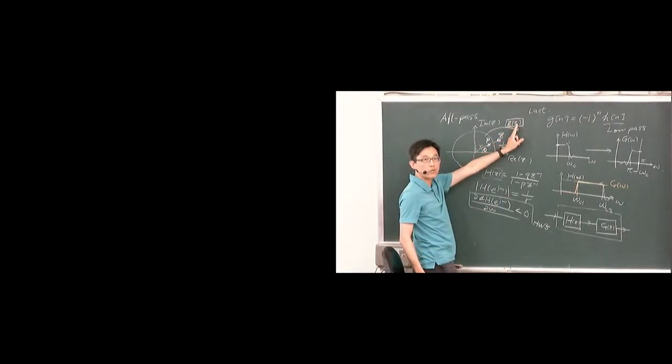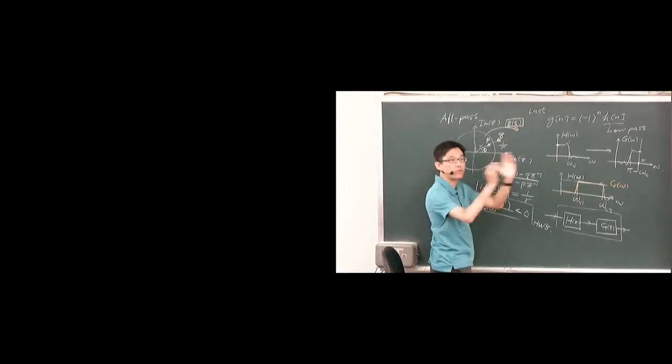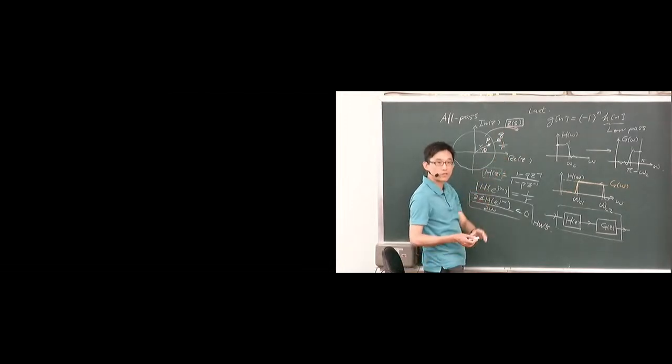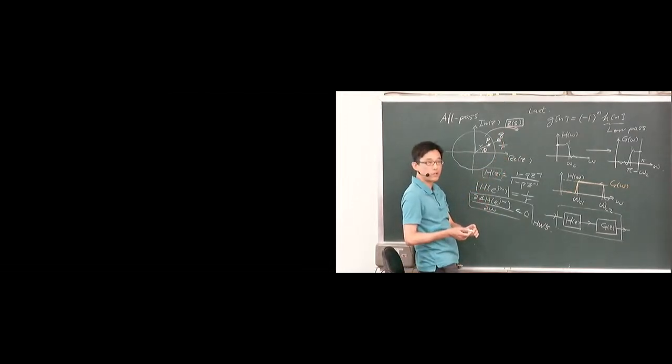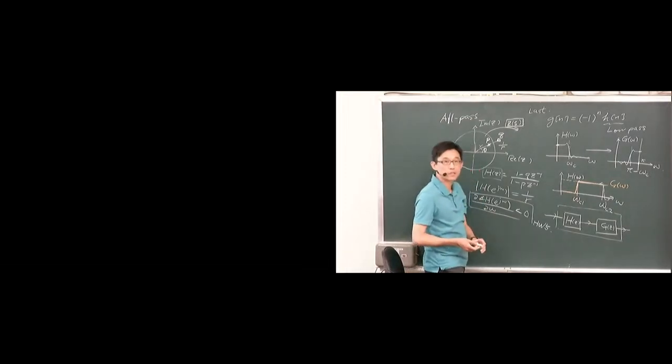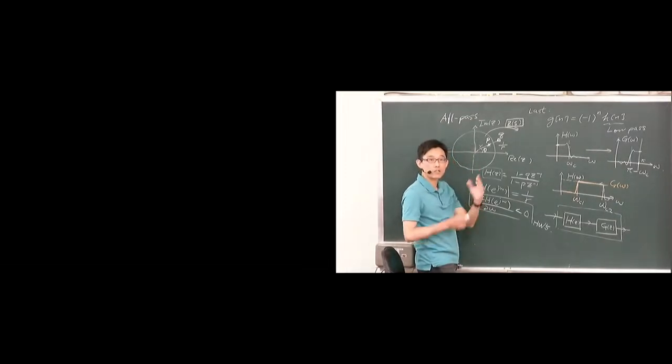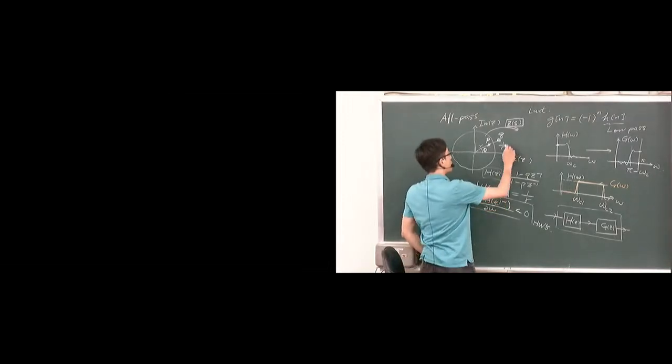Originally, when used in the forward way, when we designed the Butterworth filter, we expressed s as a function of z. But now we use the inverse function, because the bilinear transformation is bidirectional, basically invertible.